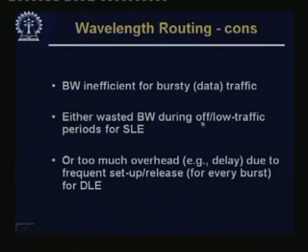So, the busy time versus the lean time may be of the ratio of 1:500, something like that. That is why this becomes an inefficient way. So, either there is wasted bandwidth during off or low traffic periods for SLE, or too much overhead, that is delay due to frequent setup and release in dynamic light path establishment. That means, if you want to put it down and then set it up again, in that time frame this becomes too much of an overhead, because if you remember, for setting up a light path we require maybe tens of milliseconds. So, you cannot do it very fast.